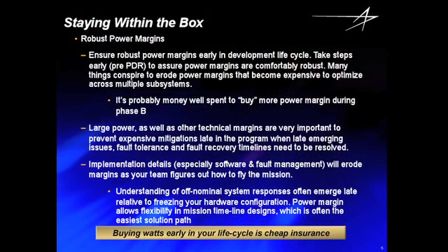Okay, of all the margins that you should strive for, my personal opinion is this one is at the top of the list. Power margins, right? Given a choice, I will buy watts early in the program because I'm going to need those watts later. Your engineering staff will do their level best to tell you what it's going to take, how much power you're going to need, and you know what? It's not going to be right. It's going to be wrong.